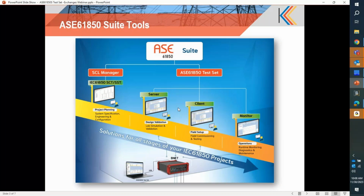We recently added client support. Previously we only had server simulation capability, and today I'm going to demonstrate the client mode of operation using exchange mode. At the bottom of the screen, you'll see a test set accessory that is in development and expected to be released in the next few months. It's called a BNet. It's a 61850 specific protocol analyzer, and this will provide sampled value capability.